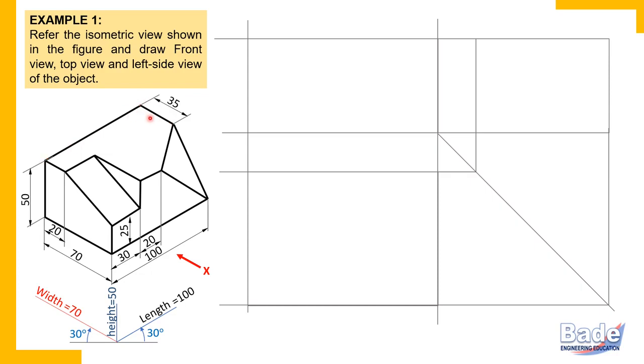That means this angle, even if it doesn't appear 90 degrees, we are sure that this angle is 90 degrees actually. You know that in a three-dimensional diagram, shapes get distorted, angles get distorted. So this angle is really 90 degrees. This principal edge is parallel to length, this principal edge is parallel to width. So that means this surface has two perpendicular principal edges. So this is a principal surface.